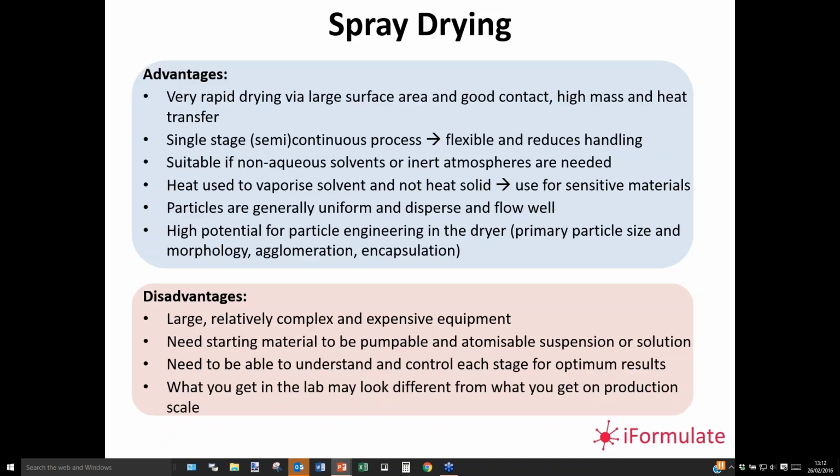So liquids tend to be at least 40% by weight, often above 60%, in order to be able to pump and atomize. And like any operation, being able to scale up from the bench to full-scale plant is not easy either, and this is very true for any particulate process. This becomes more challenging as the particle size increases in general.